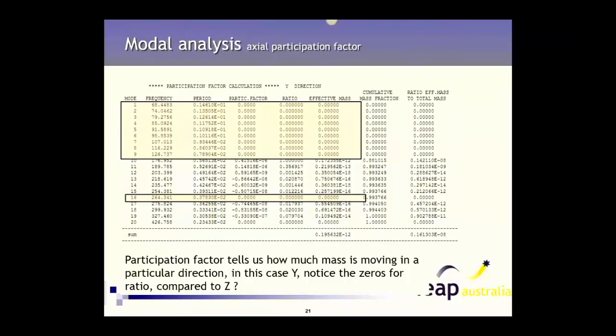Because those axial modes are going to be significantly higher than the bending modes, you're going to have to capture quite high frequencies to pick those up. And because they're quite high, it's highly likely that they'll damp out quite quickly. So there's no point even trying to capture those particular modes, because they won't be present in your response, especially if you add damping to your solution.